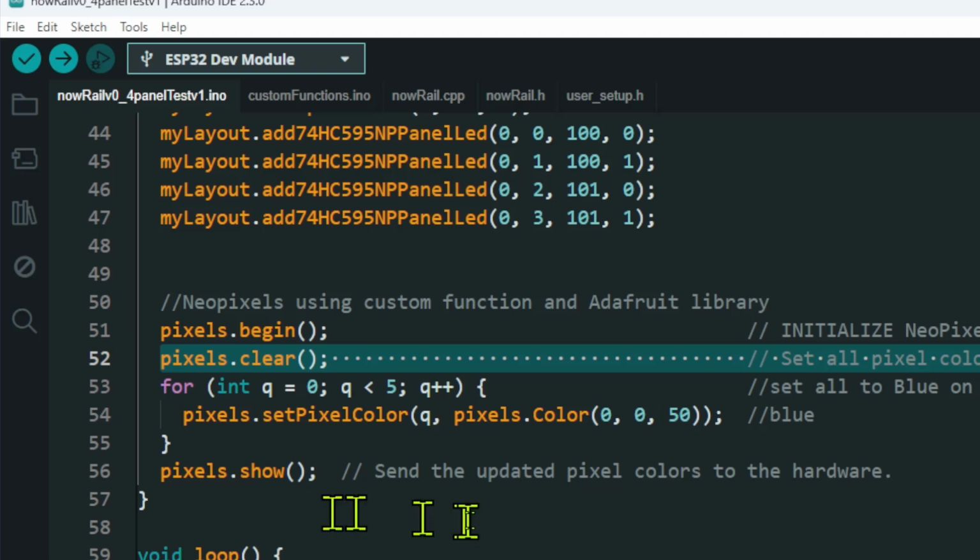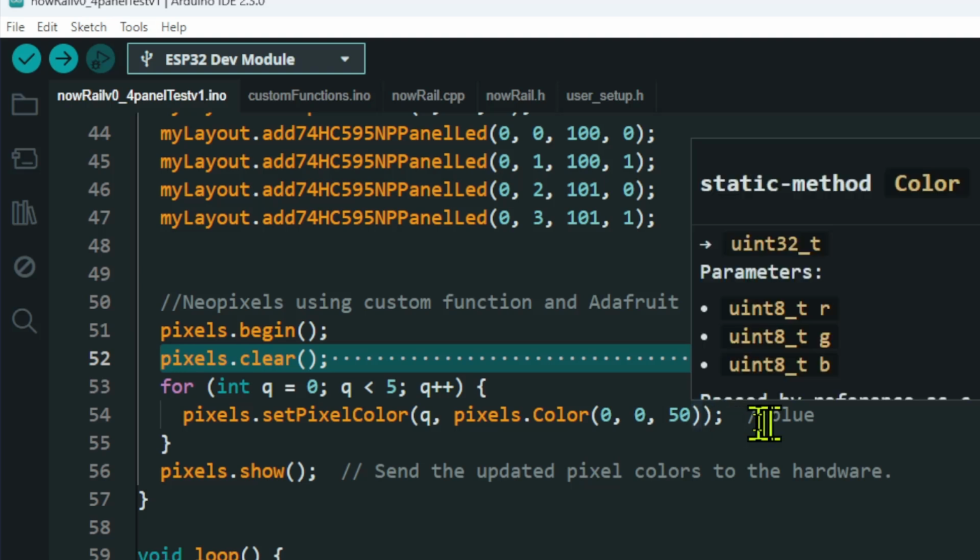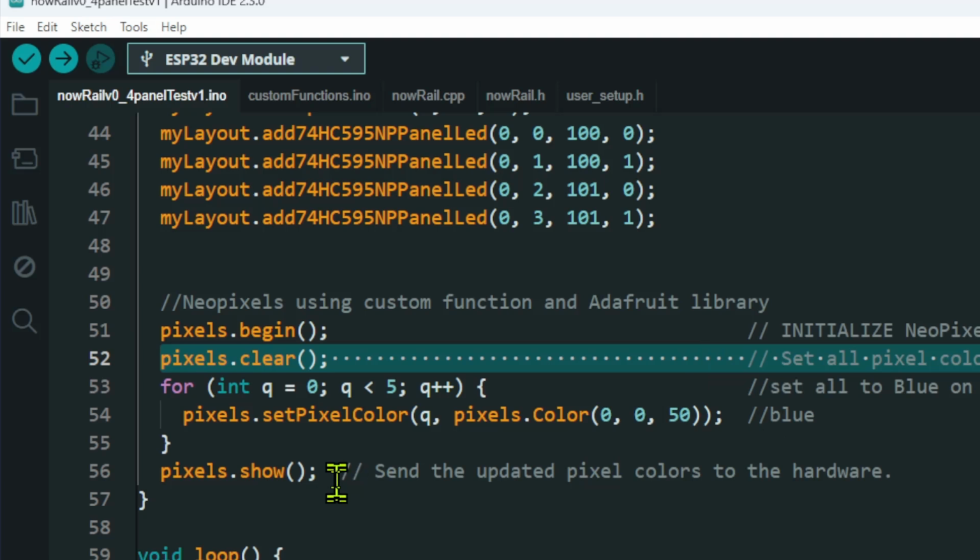And then what I do, this is something I've always done with Neopixels on my control panel, I actually set them to blue. Once I've worked through the 5 Neopixels in my demo strip, I set them all to blue, and then this command, pixels show, displays them basically as blue LEDs. This, if you like, sends the data through. This tells the system when to switch that new data on. So that's what it does when the system sets up.